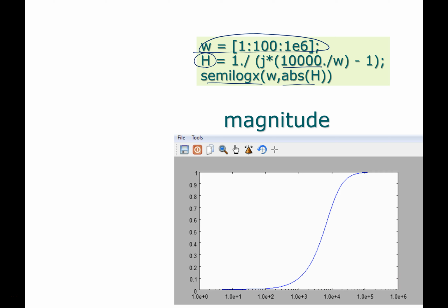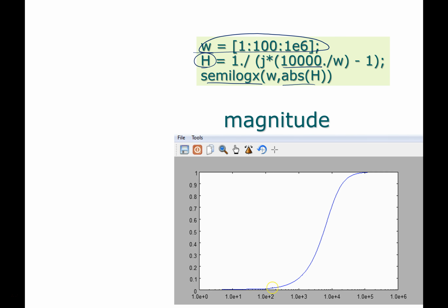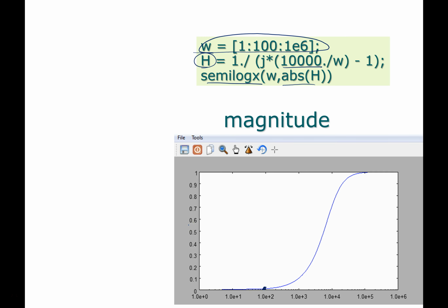So you're hitting this thing with a frequency of 100 hertz. You look at the system function and identify, here we are at 100 hertz, and my amplitude is pretty small there. It's telling you that you're only going to get an amplitude gain of 0.01, suppressing that signal if you hit it at that frequency. But if you hit it with a signal at a frequency of 10 to the 4, about 70% of the energy, or 70% of the voltage, is going to get through.